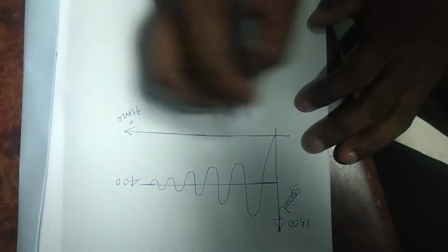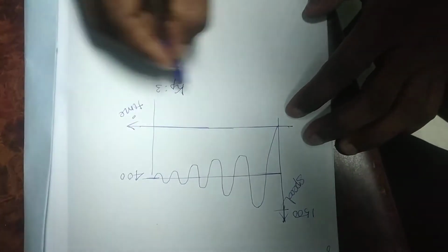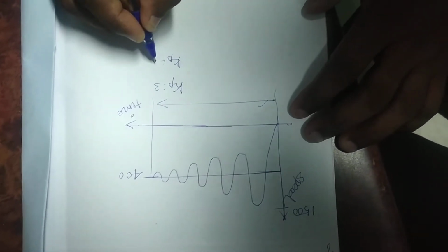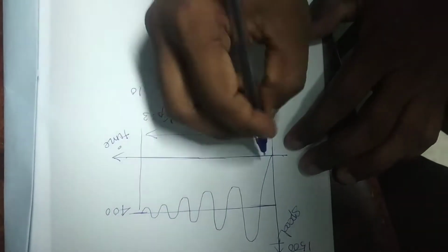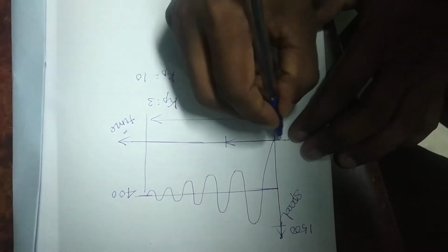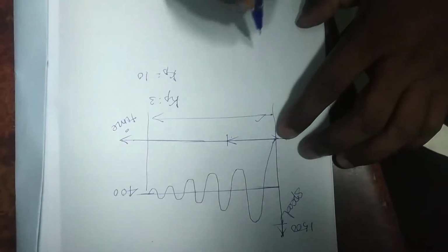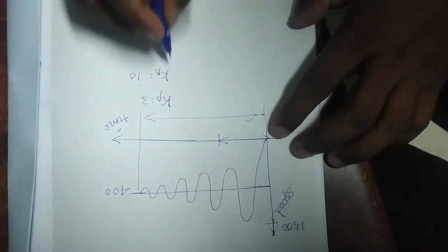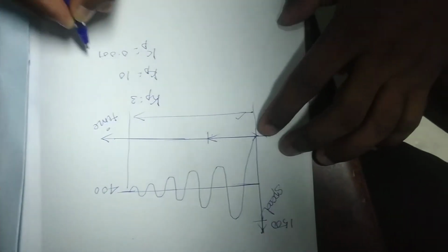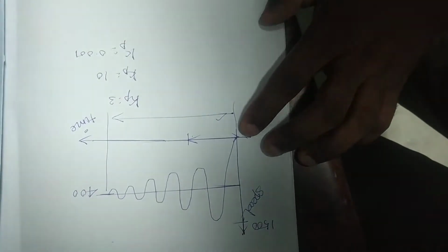If you take the Kp value as 10, within this time the system reaches our required speed. It takes only a short time to obtain our target value. If the Kp value is 0.001, it takes 1 or 2 months to obtain this speed. That is the importance of the Kp value.